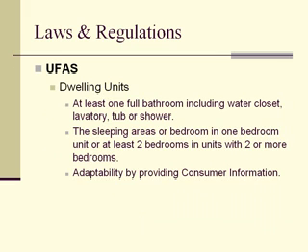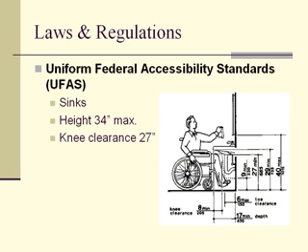And now, in the case for the Pensacola Area Housing Commission, we opted for providing fully accessible units, primarily because if you leave something that can be adaptable at a later date, there's also the possibility that the modifications might not be done right, and it might not be in compliance, and also going into providing information for the consumer. So we opted for providing accessible units, which ultimately will provide just the level of access that is required at this point. Okay, so different requirements as we mentioned.